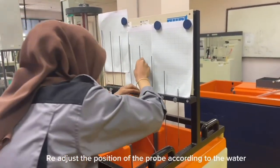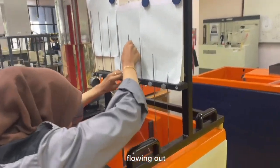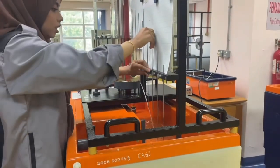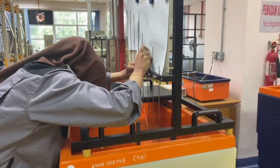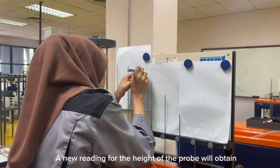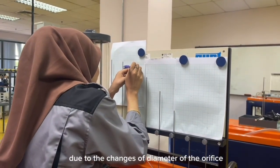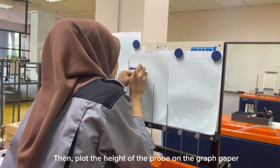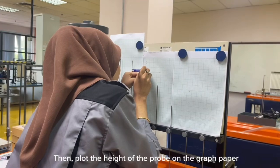Readjust the position of the probe according to the water flowing out. A new reading for the height of the probe will be obtained due to the change in diameter of the orifice. Then, plot the height of the probe on the graph paper for all readings.